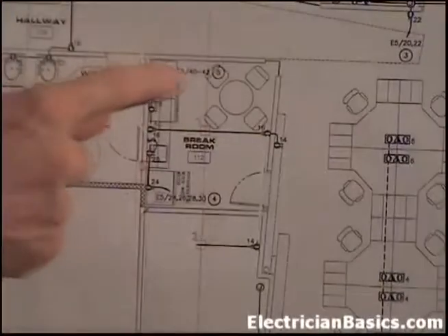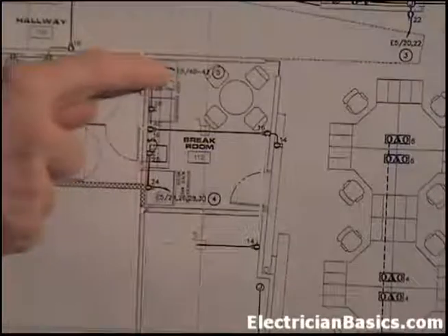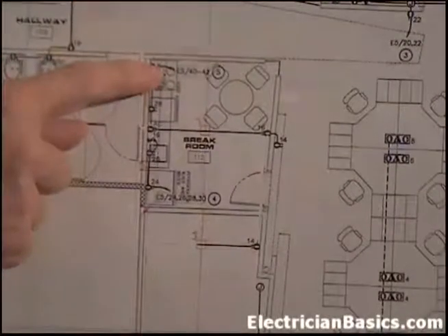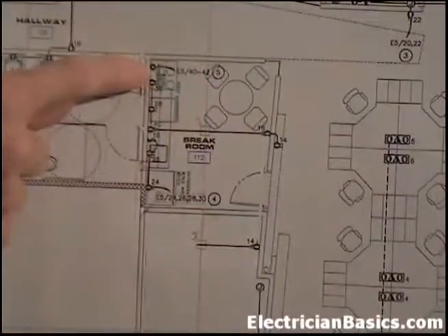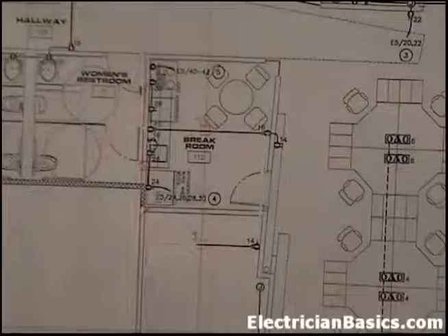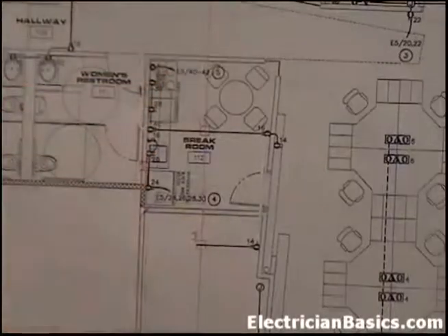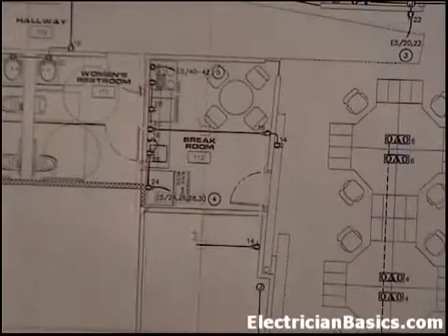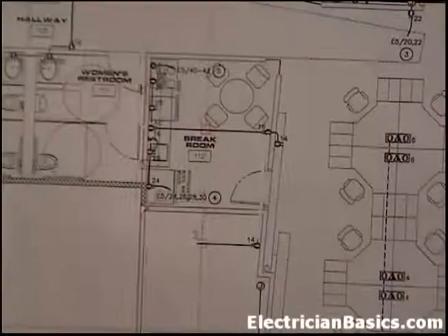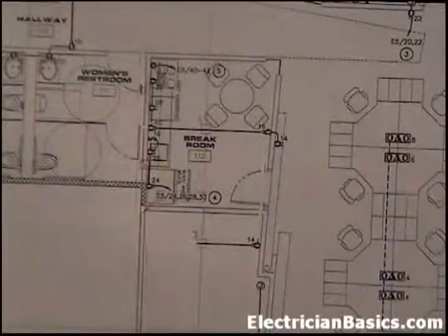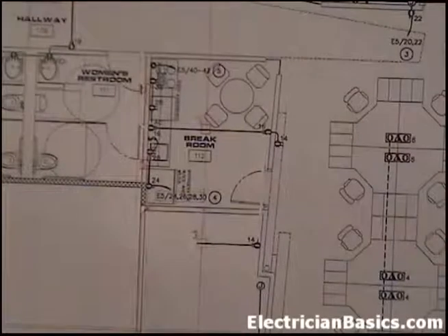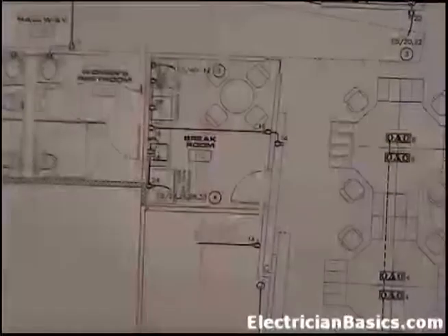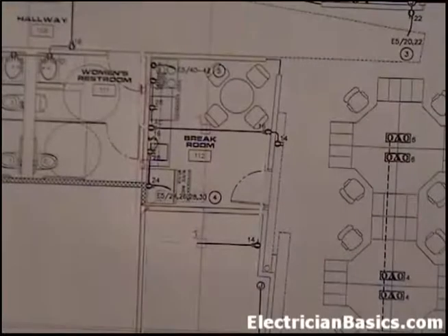Up here for E5, 40, and 42, we didn't really have to do any redlining because it says from here make a home run, and it's just these two circuits in the conduit, and it's basically from this plug to the panel. There aren't any junction boxes in there, so you don't have to do anything. But that also ran along this wall here on the unistrut, and with note 2 somebody could easily figure that out. Again, you don't have to put everything on the red line drawing. It's just that note 22, remember, said the changes, the significant changes. That's the kind of things that we have to put in here. What I want to do now is kind of move up to the reception area because we have to look at a few things there with some redlining.